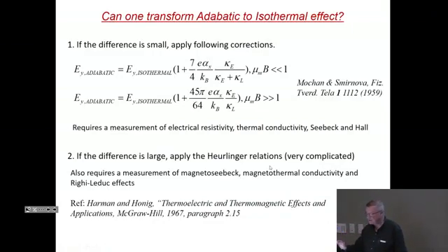The correction is at high field or at low field. High field is when the product of mobility times field is larger than 1. Low field is when the product of mobility times field is smaller than 1. When we do data analysis on our cryostats, I always quickly calculate what the correction factors are. That's called NINA in the programs.